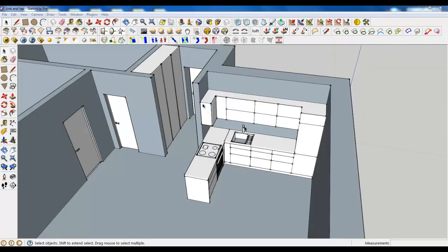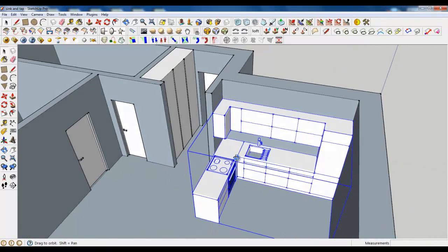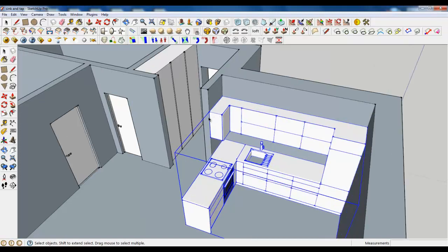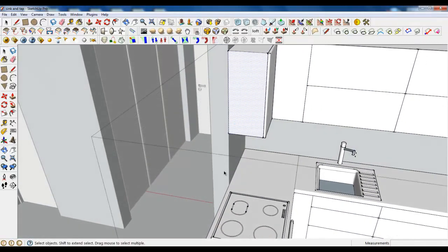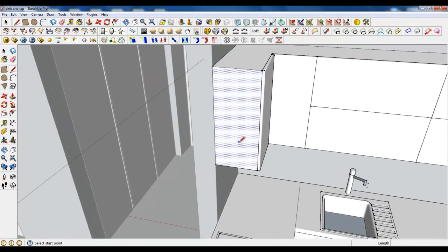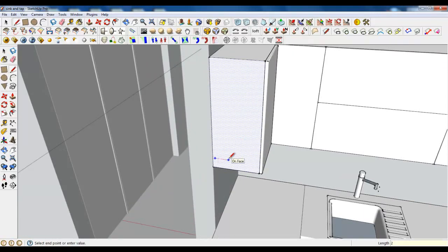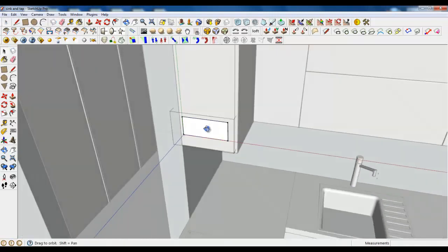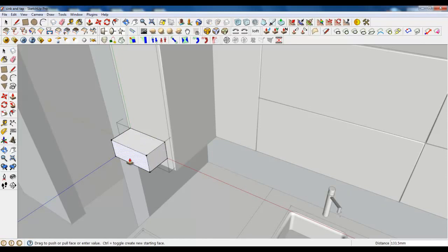We are back to the tutorial, and now I will show you how to create a chimney hood and shelf behind it. So let's begin. Open our group and create a line 215 length. Perfect. Close the rectangle. Make a group and extrude it by also 250.